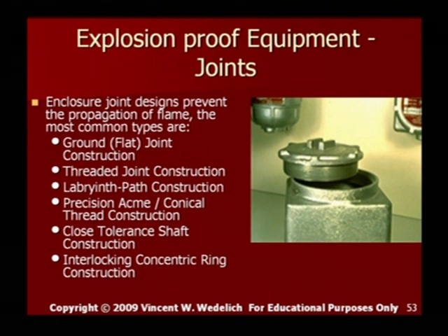Another thing is you only need 5 full threads or 7 full threads, depending on your area, on that box. So you don't have to torque the lid down. All you have to do is bring it up flat to its surface, to its gasket, and then just kind of hand tighten it. You don't have to actually torque on that box lid.